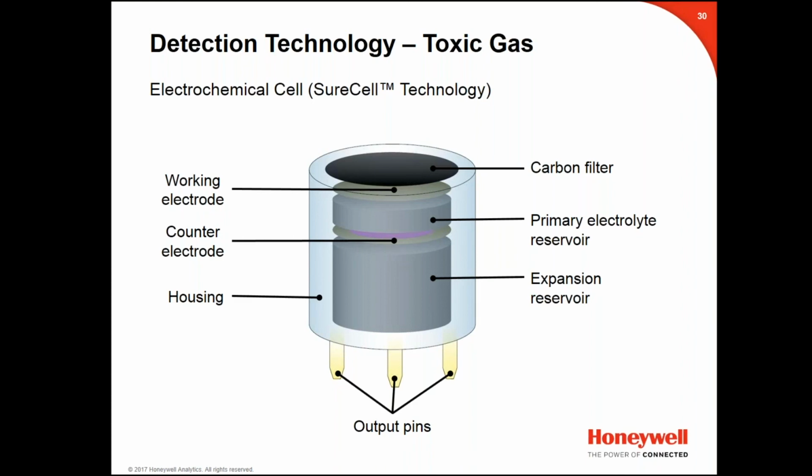So for most of our products that I deal with in the industrial premium portfolio, we're Class 1, Division 1 and 2, Groups B, C, and D. When we talk about Europe, that's generally Ex d or flameproof, and it can be either Ex ib or Ex tb, depending upon the requirements of the specific application. ib is intrinsically safe. And then generally followed by, I think it's IIC plus H2 for most of what we do, with anywhere from a T4 to a T6 temperature rating.